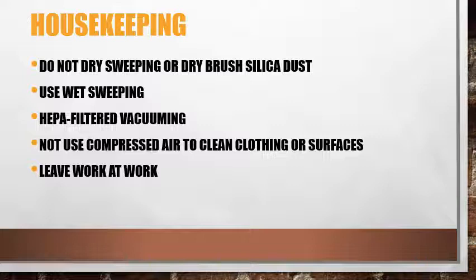Let's talk about some housekeeping practices that can help us be protected against silica dust. Do not dry sweep or dry brush silica dust. Use wet sweeping so it doesn't push it into the air so then you can breathe it. Or instead of sweeping, you can use a HEPA filtered vacuum. Vacuum up the silica dust.